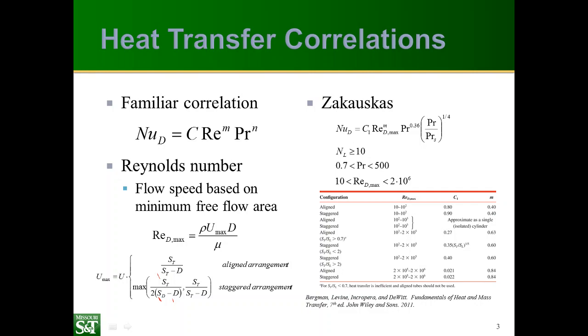Now, in these kinds of systems, the fluid temperature can change from inlet to exit. We always want to evaluate the fluid properties at the average fluid temperature rather than the inlet temperature or the outlet temperature, to avoid any problems with using fluid properties that are not close to the average value.